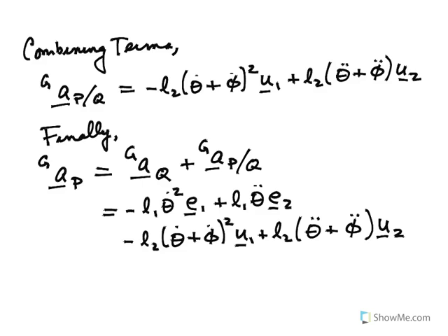Now you'll notice again that everything is not expressed in a single coordinate system or a single basis. It's expressed in two different bases because each piece of the vector is more conveniently differentiated to obtain rates of change using a different basis. There's no need at this point to combine everything into a single basis. At some point later on, when we're actually starting to do kinetics, which I'm not going to talk about now, things often need to be put into one coordinate system. Sometimes they don't. You can just leave them, but you can do manipulations without having to actually do full transformations.